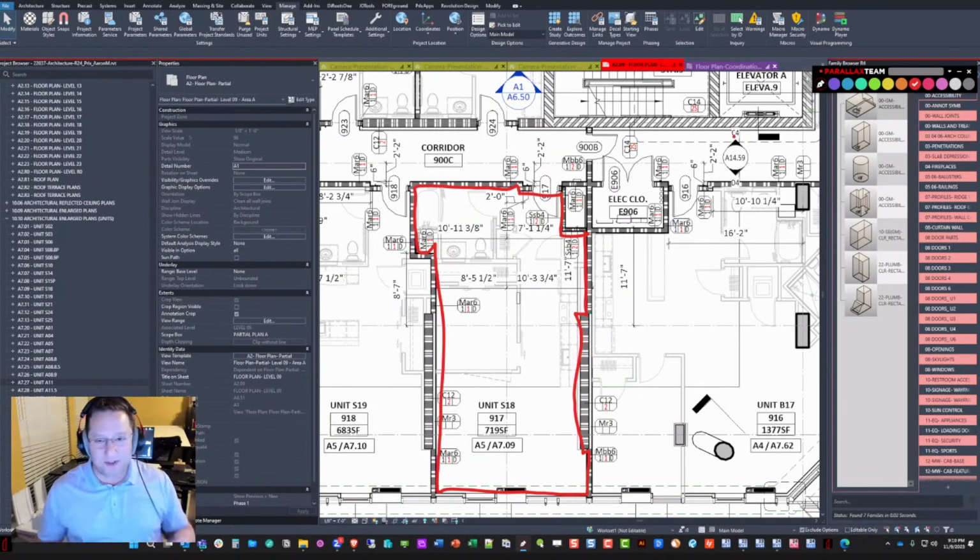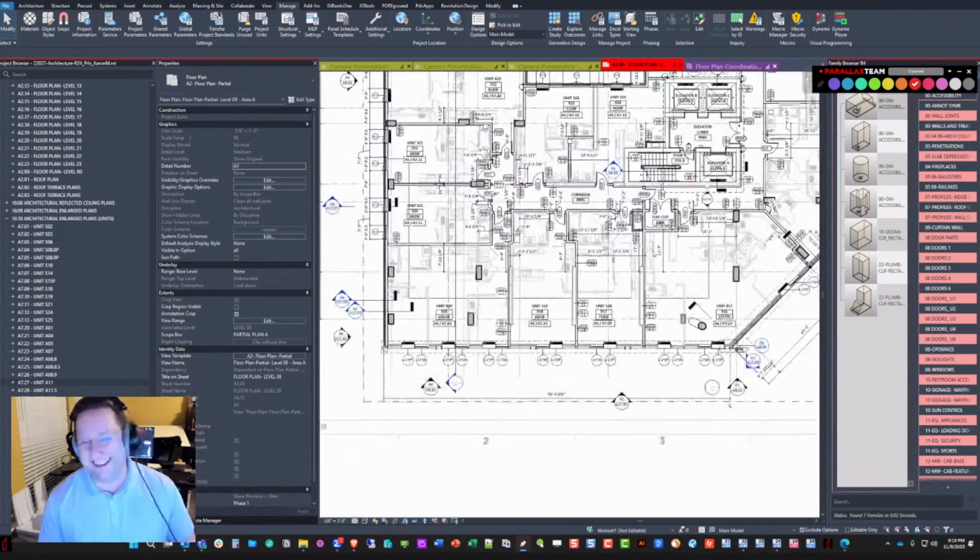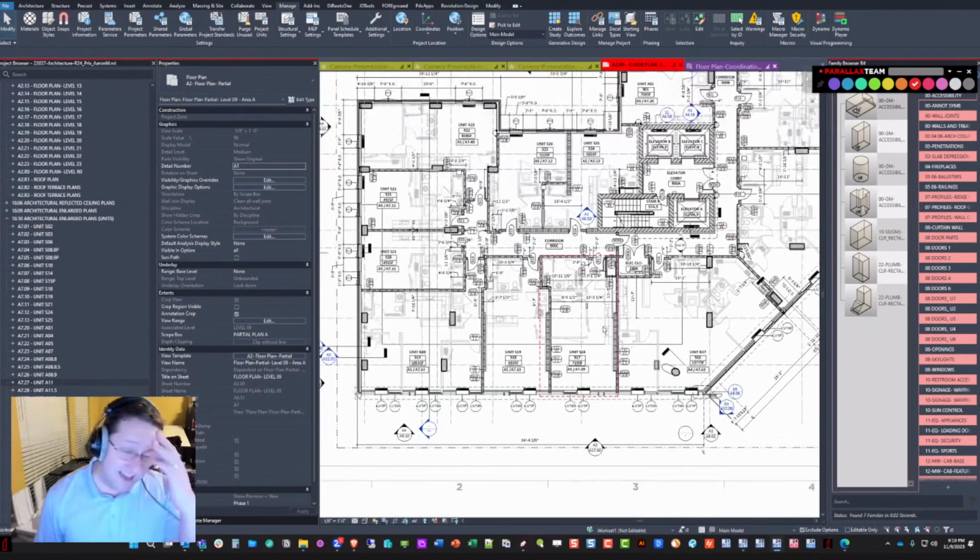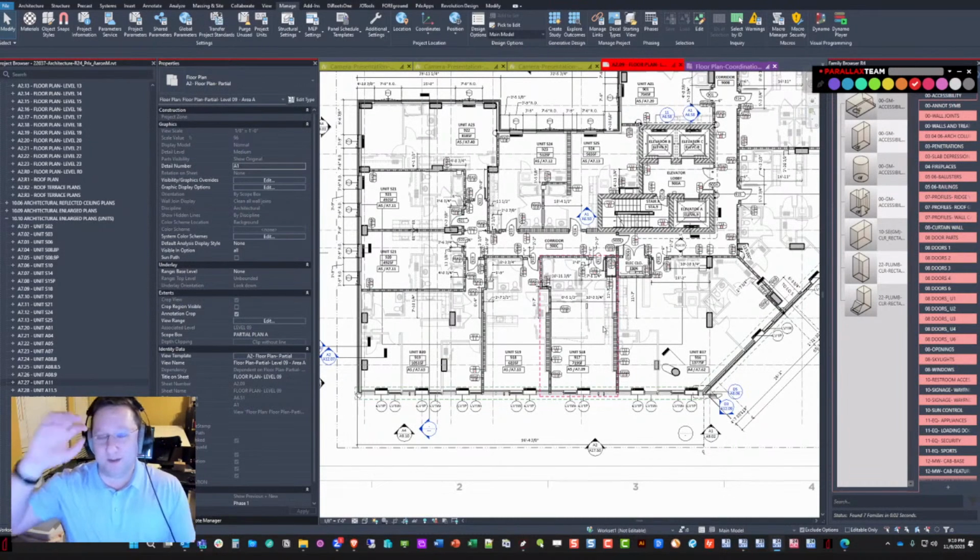Yeah, so most of our clients are like, reference planes, and reference planes are great, and we'll put them around the entire unit, and I die on the inside because reference planes automatically go the whole height of the building, and again, they show up everywhere. They do show up everywhere, and this is where people are like, groups suck. I accidentally grabbed a group and I added it to another group by accident, and what the heck? And my groups broke apart. It's the reference planes. So this is what's going to make everybody cringe, and I love it.